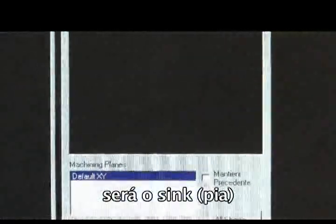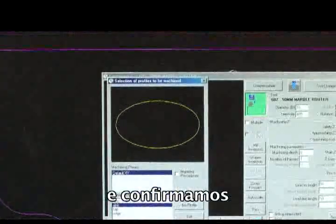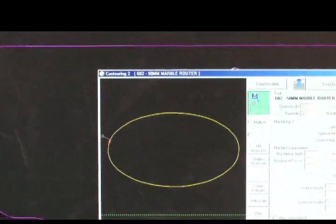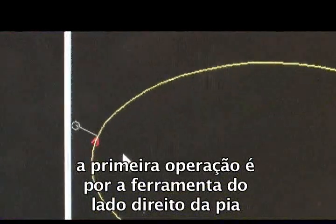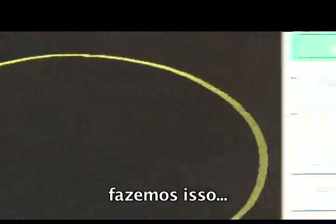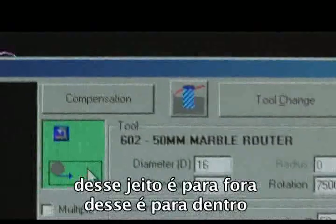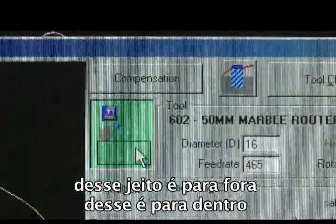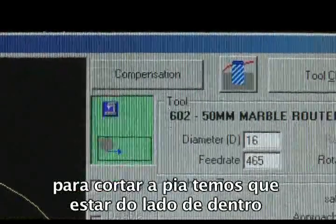We confirm, and now we choose which shape we want to use for this router. It's going to be our sink, and we confirm. The first operation is to put the tool on the right side of the sink line. We do this by activating this green square. So that is outside, this is inside. To cut out a sink we need to be on the inside.